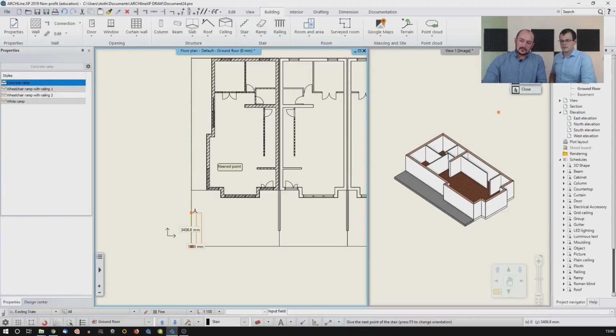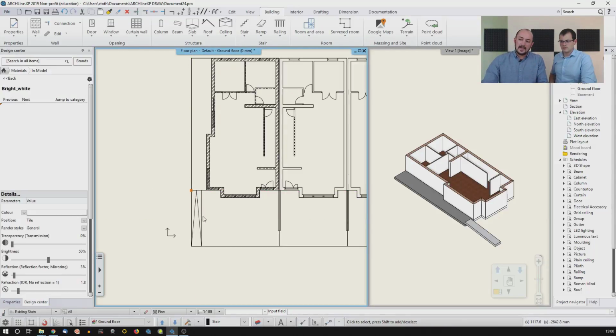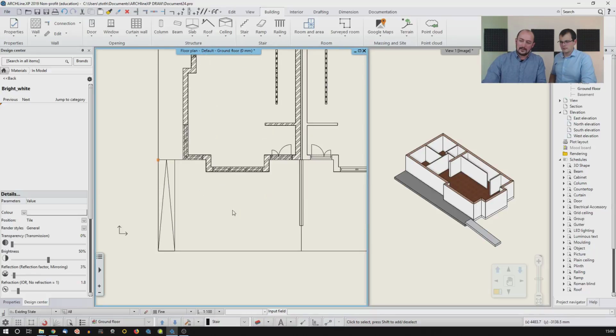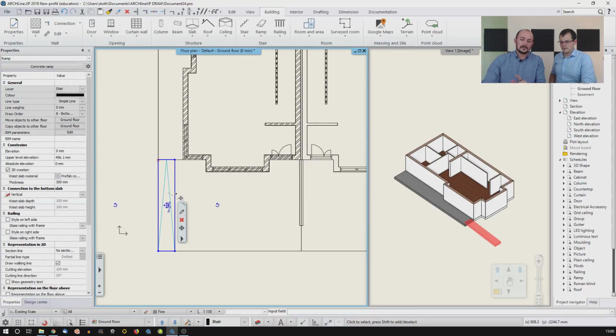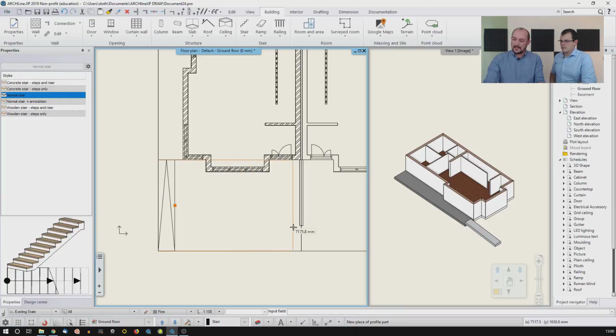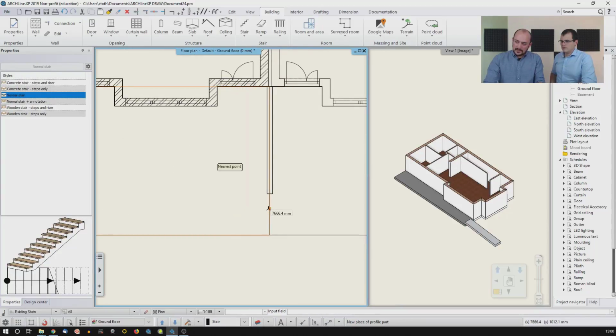And you just pick the 2 points, the starting, the lowest point and the highest point. And now it's a little bit narrow. I need to cover this whole area. So I select it and I click on the contour, and on the contour I can see that there is an edge menu. This gives you the options that you can do with the edge. You can actually offset the edge, and you can just snap it to the line drawing here and click there.